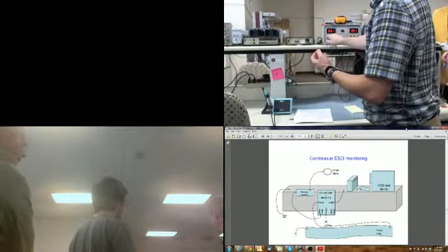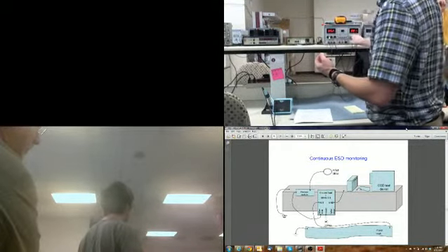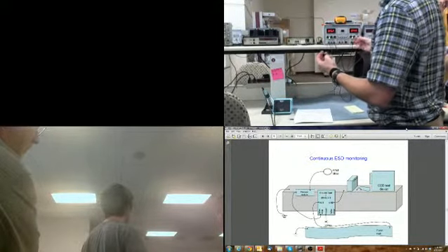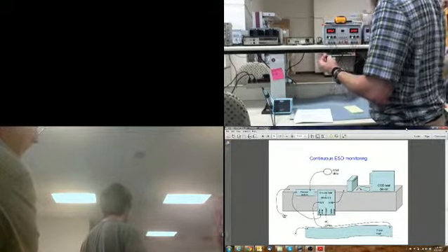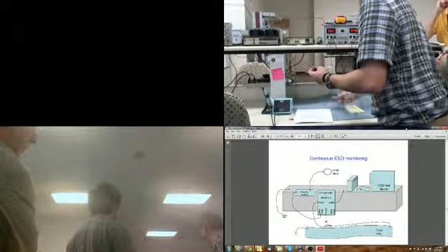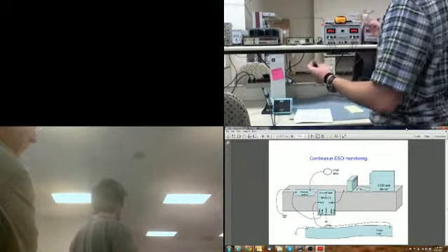Over here I have 5 volts. But now you're also going to have a voltage on this side too. It's actually going to be about 10 volts because they're in series now. Does everyone see that? About 10. So you add the 2. If you're in series mode, then you're going to add the 2.